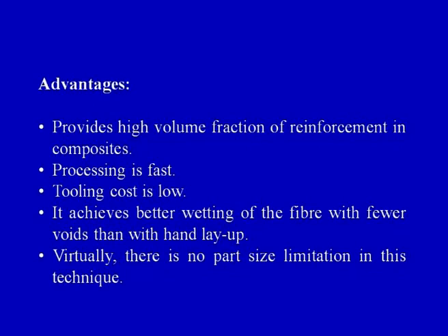So we want a higher fiber volume fraction for the composite. The spray layup process provides us that advantage, that we can afford to have a high fiber volume fraction using this process. The processing is fast, tooling cost is low, it achieves better wetting of the fibers with fewer voids than with hand layup. So the voids that are present in the hand layup process can be avoided by the spray layup process. Virtually there is no part size limitation in this technique. So we can even make a product of the size of this room using the spray layup process.